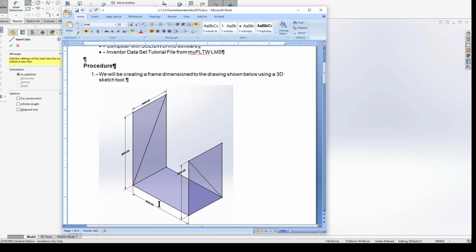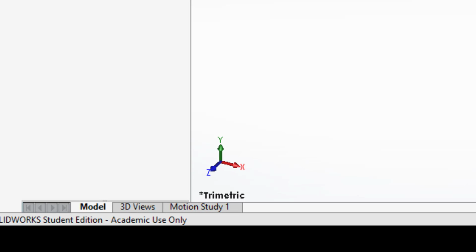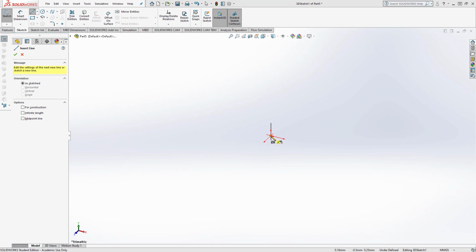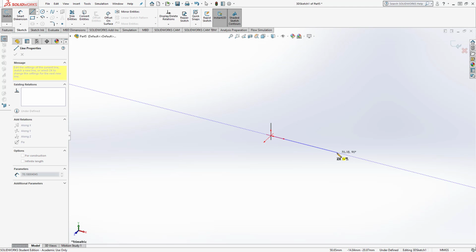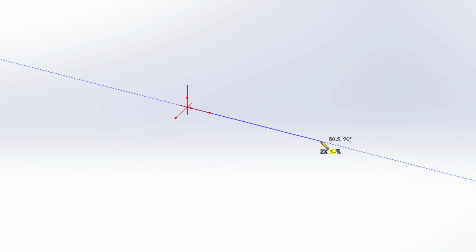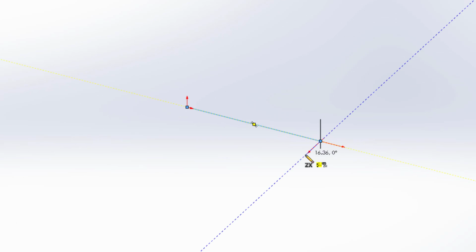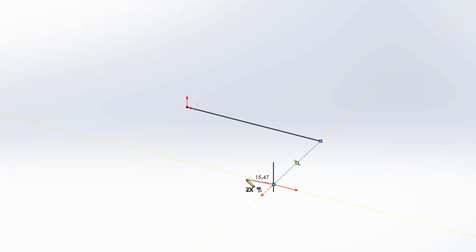And I'm going to sketch a rectangle in the XZ plane right here using a series of lines. So there's my XZ plane. So I'm just going to sketch that out. So I see ZX by my icon, and I'm going to click to drop my line onto the origin and just stretch it on out. Right now I'm along X, and you'll see that my glyph shows that. Drop a line. As I come back, you'll see that I'm along Z right now, and you'll see my glyph shows that also. And I'm dropping back, I'm along X again.